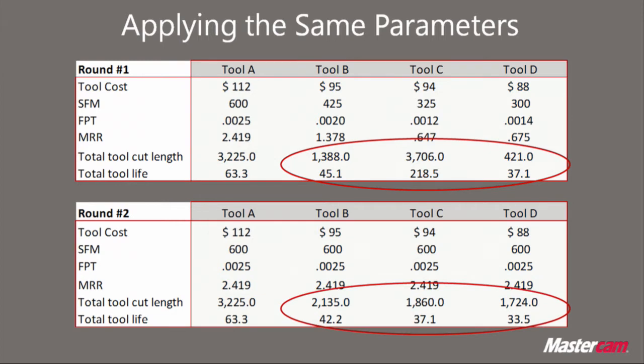But when you look at it, we've taken a hit on tool life. We're down to 42 minutes, 37 minutes, and then 33 and a half. So that's pretty respectable. The cut time, the cut length itself has also dropped and increased depending upon the type of tool and which tool we were actually using.